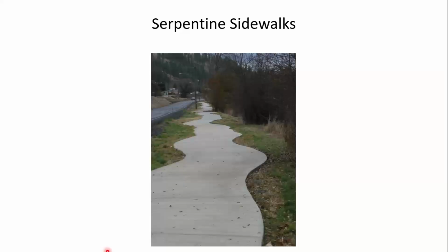So they want to be able to get from point A to point B, as we talked about yesterday, kind of with the path of least energy. And a serpentine sidewalk, to me, doesn't provide that. But also, if you think about some other considerations, for example, ADA, think about a blind pedestrian, excuse me, who's relying on the edge of the pavement, for their shoreline to navigate.